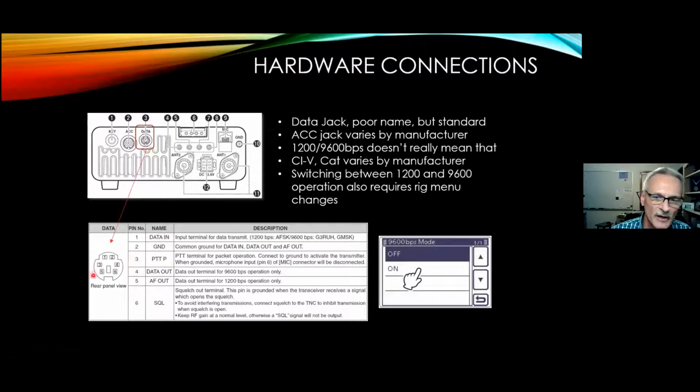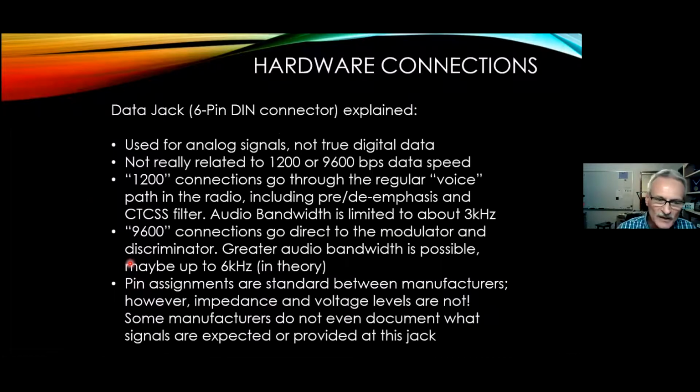The other bad thing about this connector is that we don't know what parameters the manufacturer of the radio wants for that connector. Sometimes you will see it documented well in the owner's manual. Often you will see that it does not tell us what signal level they want there or what the impedance is. It may not say anything at all about it. So you may have to do some experimenting to figure out what the correct level is to get the performance you want.